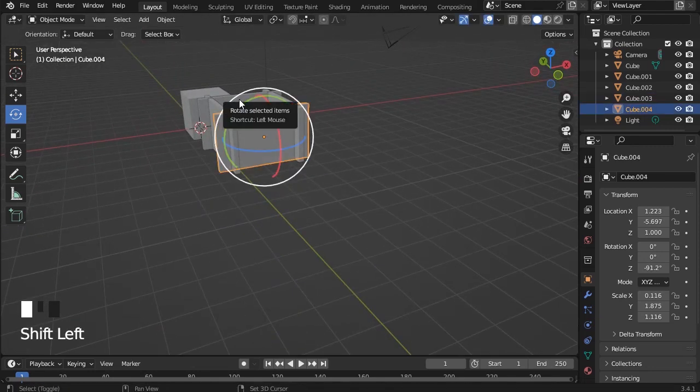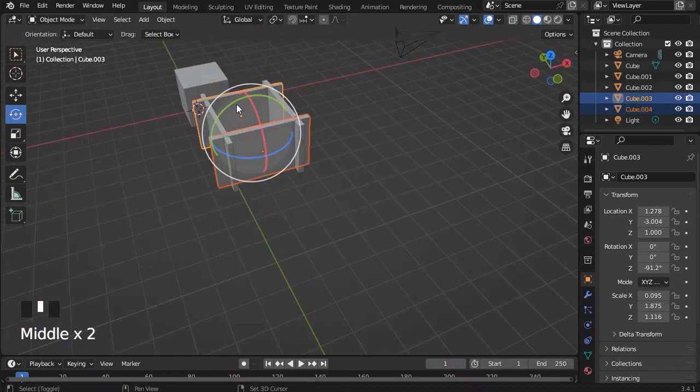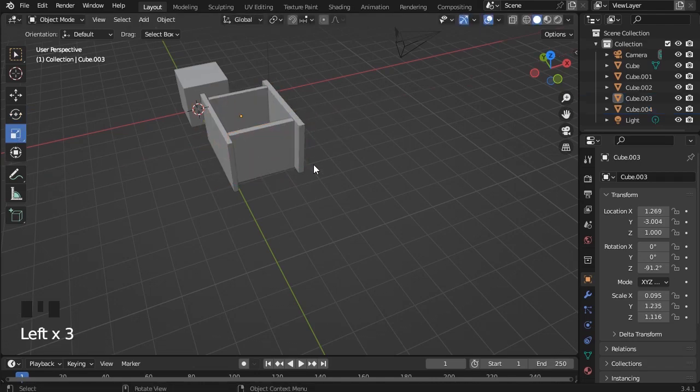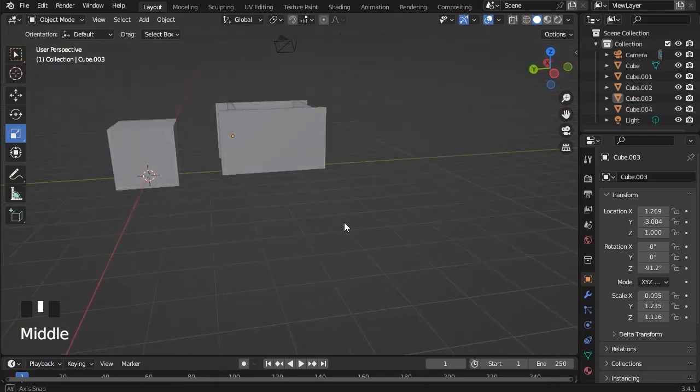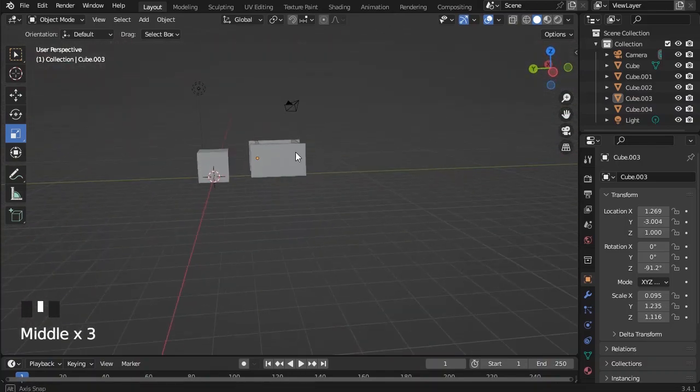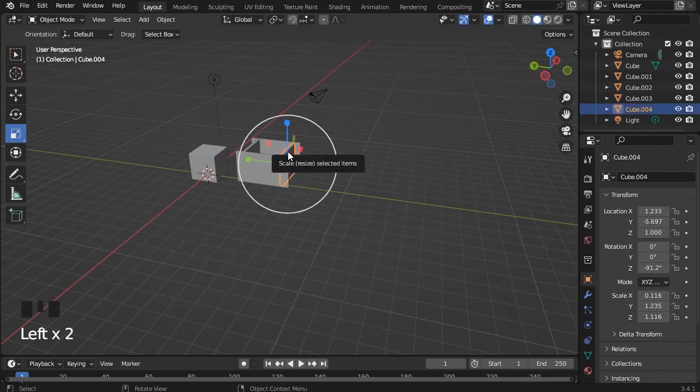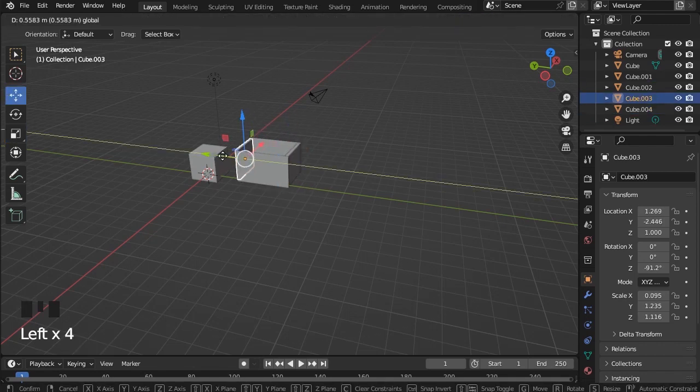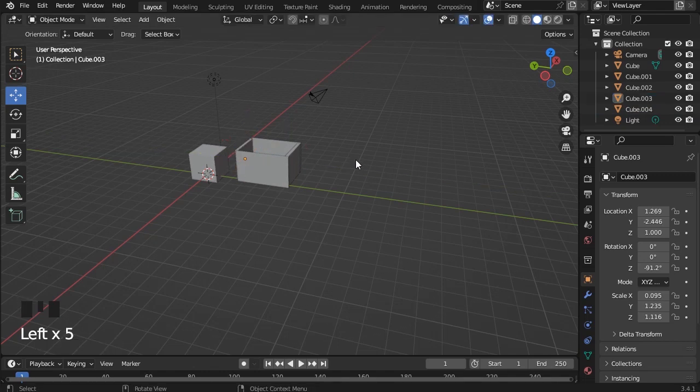Oh yeah, if you want to select multiple objects, you click on one object, and you hold Shift, and then you can select the other object. And then you can change the 2 properties at once. So you're now able to make houses and things that look like cubes. I was able to make an entire apartment using this skill.